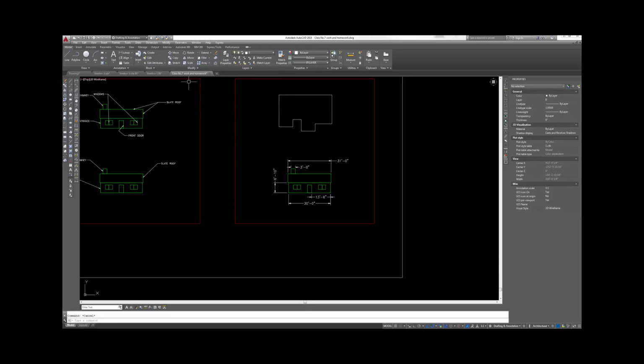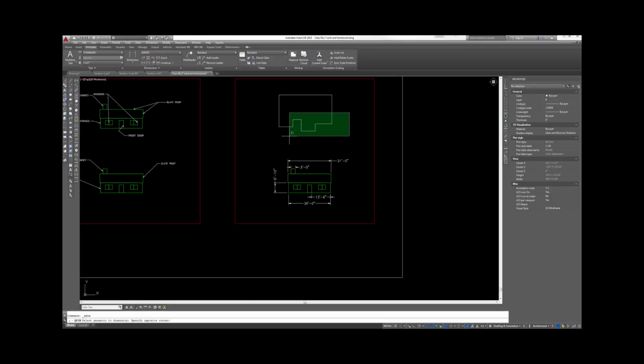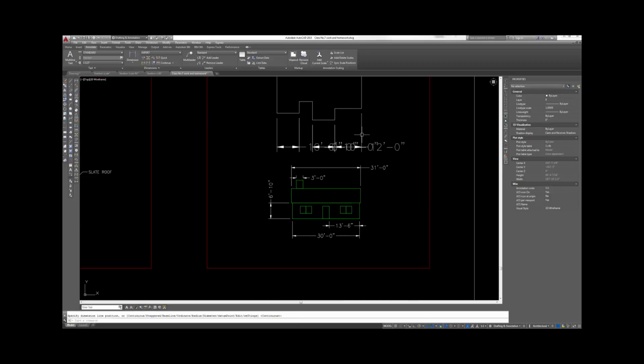When we do dimensioning, there's the Annotate tab up on the top here. It gives you many more options for your annotation. One of the dimensions here is your quick dimension. If I select the quick dimension, I come over here, just pick, and I cross this whole area and hit the space bar. It gave me dimensions for every single one of those.